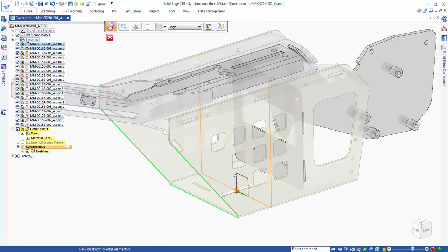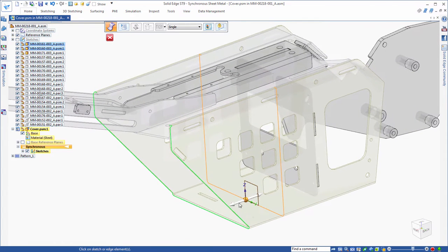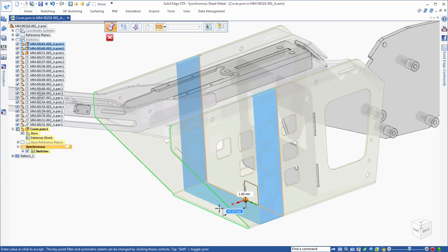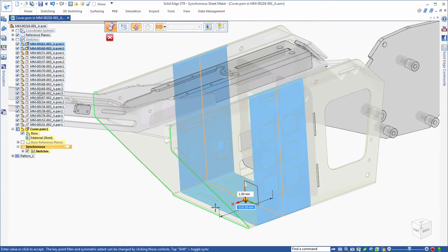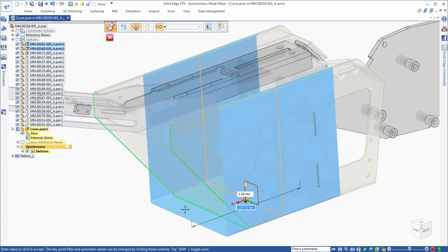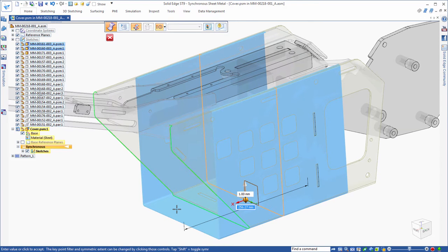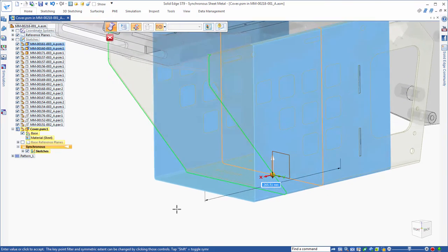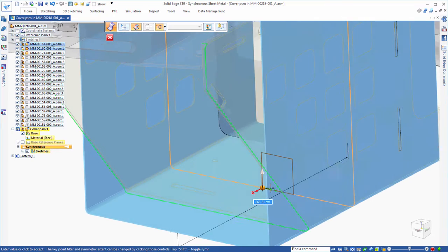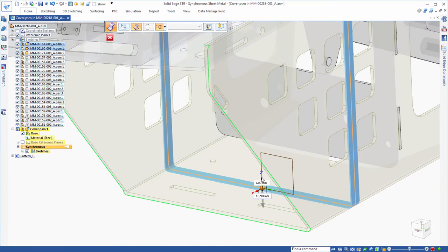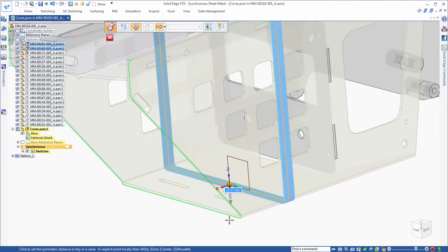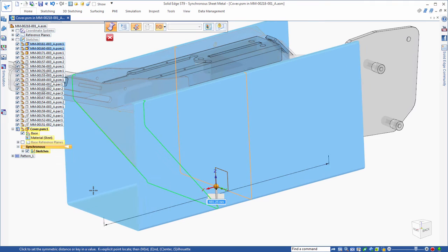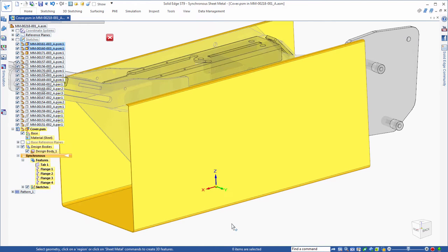And notice I'm already in the contour flange command, so all I have to do is start selecting a direction, start dragging the contour flange. In this case, I'm going to hit the shift key. I want to go in both directions. What I notice is the background parts are bleeding through the edge here, which means that really the material is being forced to the inside, and I want it forced to the outside, so I just need to pick the arrow here to force it to the other side. Now we're forcing the material outside, and I just want to completely cover that battery housing.